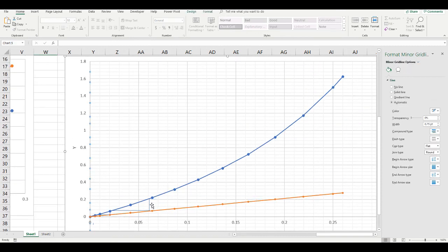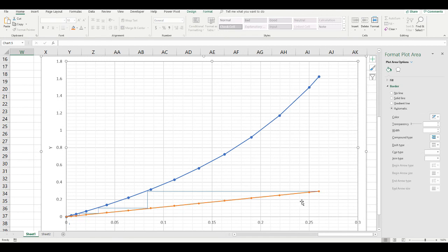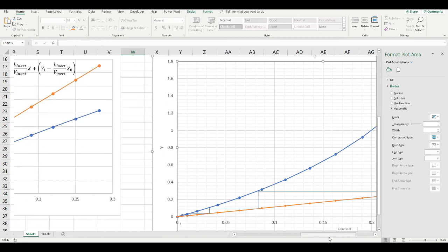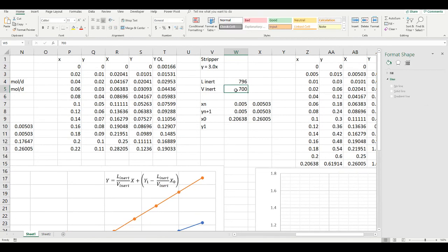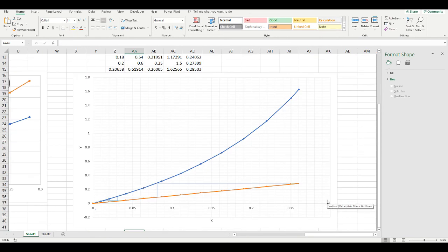So let's pick 700. Okay, so after doing that, you can see that we barely make it under the end of the line, so we just need to increase this a tiny bit more, and we should be right on the dot. So let's pick 725. After tracing the McCabe line for 725 moles per day, it looks like this is roughly 4 equilibrium stages.